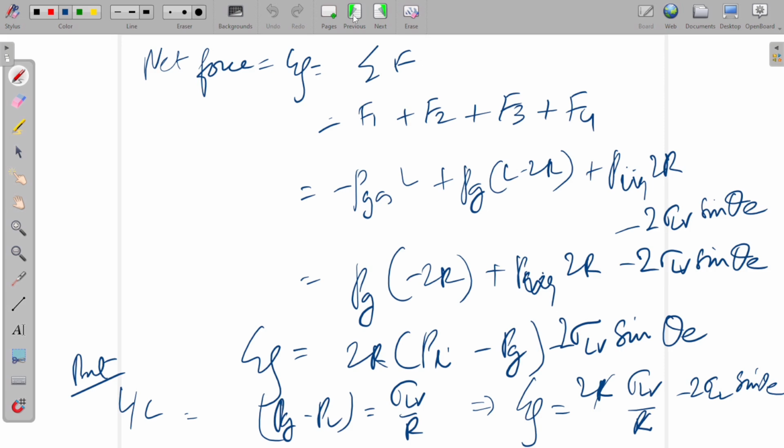Sir, do we have a boundary condition in the precursor film also? Yes, a no-slip boundary condition will be there on the precursor film. But the droplet is sitting on a precursor film, so from the droplet's perspective, it's not feeling the surface.